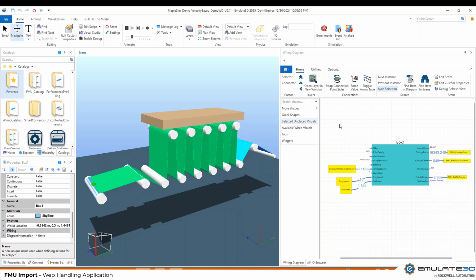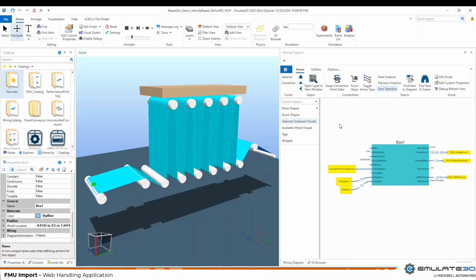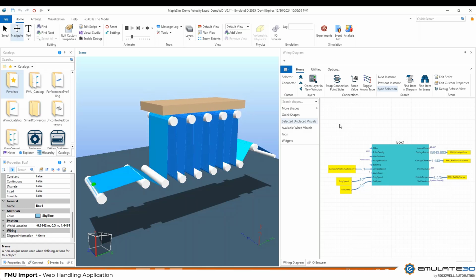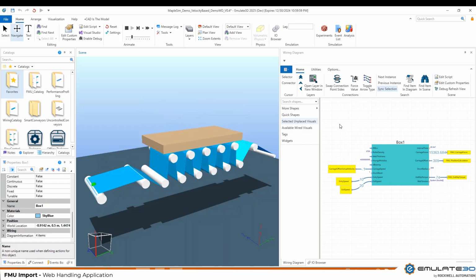The magnitude of the tension is visualized by changing color, blue being the lowest and red being the highest. In the logic, the carriage moves up with an S-curve motion profile and down with a trapezoidal motion profile. Notice how the magnitude of the tension is higher as the rollers move down with trapezoidal motion. This provides us insight into how the motion control impacts our web tension.